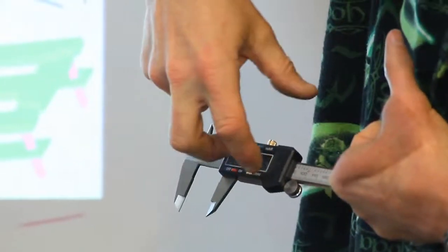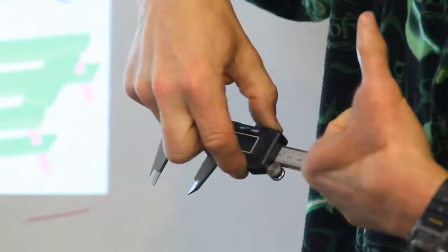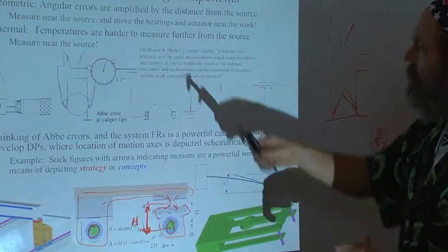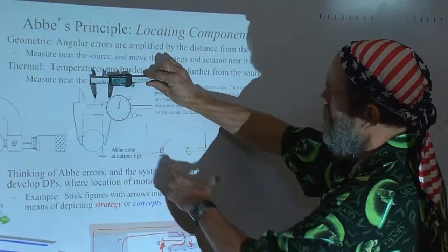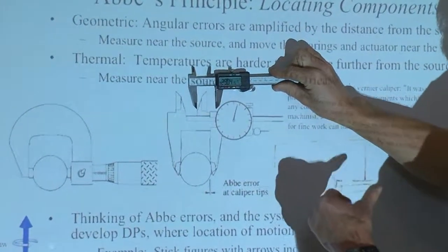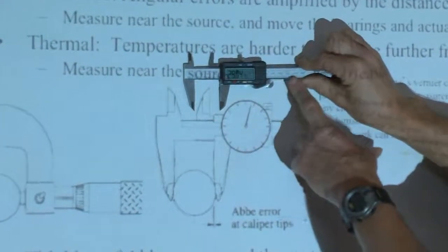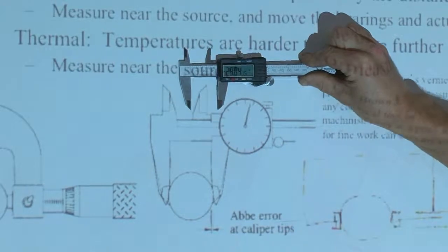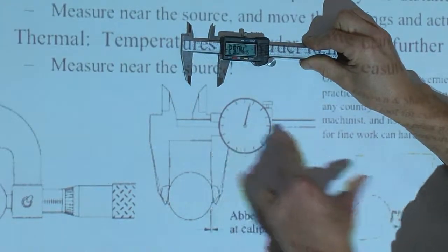So any bit of rocking in this head as it moves will cause an error, Abbe error. Now, look at the difference between this stylistic design here and this design. What do you see? You'll notice that the thickness of this rail to the length of this carriage is different than this length to this thickness.